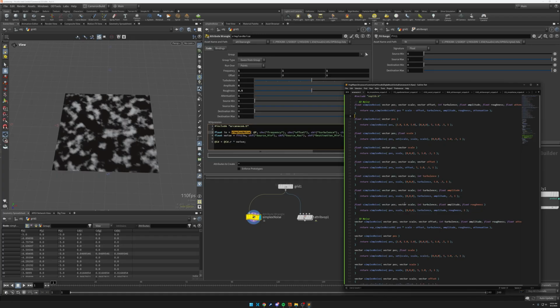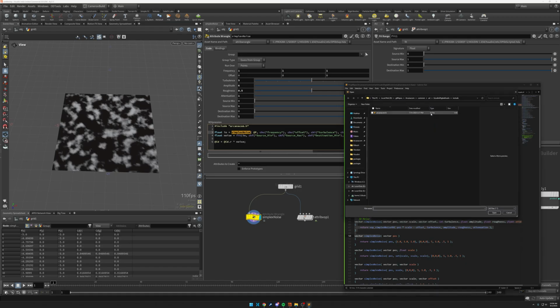All right. And it's so easy to do this. Now you just create this header file. You jam this into your header file. You put this somewhere on your disk, and you tell Houdini where to find that. And you just put that in the HOUDINI_PATH environment variable. Or like I did, I created a package. Let's see here. I'll open up.